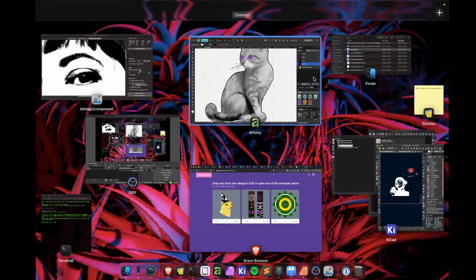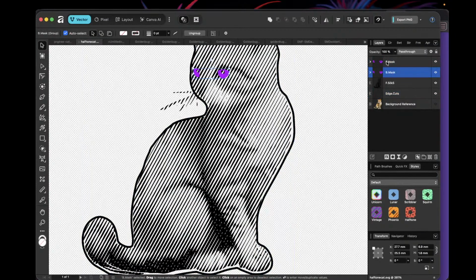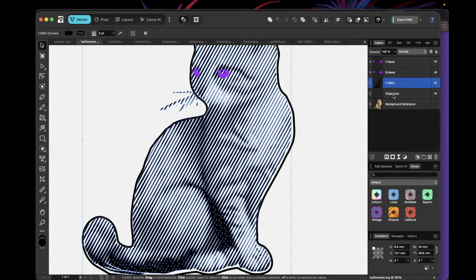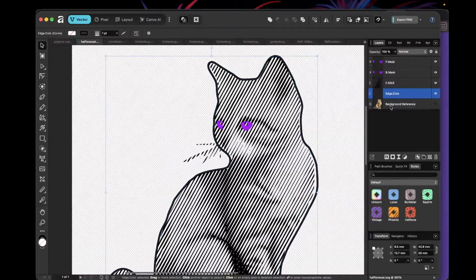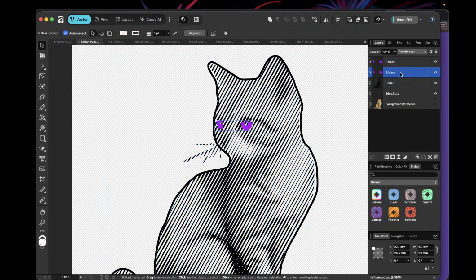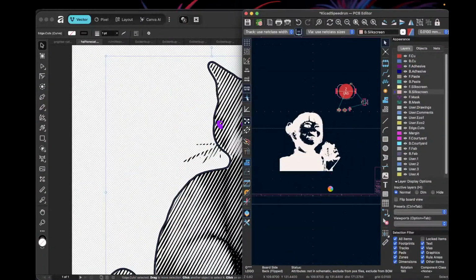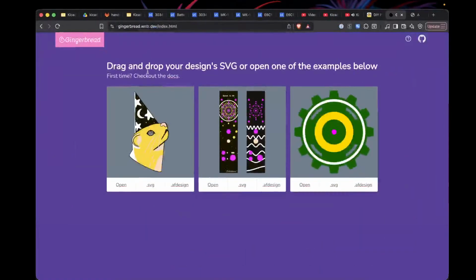And so for this, previously, based off of the instructions in that doc, I labeled it as the layers that I want this to ultimately end up as. So we've got our edge cuts, front silkscreen layer, front mask and back mask, because I want to delete the solder masks for the eyes so we can put LEDs on the back and we have some glowing cat eyes as a result. And so I did this earlier, and I saved it. Is it still grumpy? Yeah, it's still grumpy. It means that we'll go hang out over here.